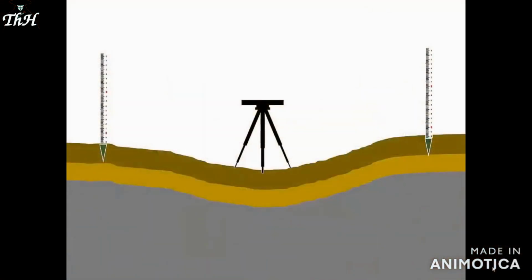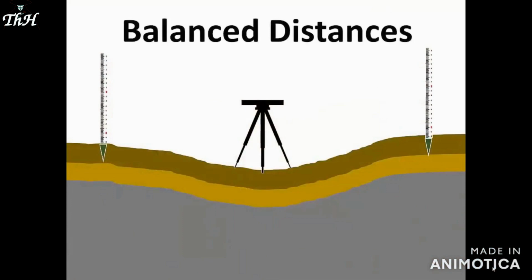Whenever you use an optical level, your first question about that instrument should be, is it properly calibrated? Keep a permanent record of your calibration notes. If the instrument calibration is over 1 year old, it's overdue for another check. Some professionals calibrate their levels monthly to ensure quality measurements.